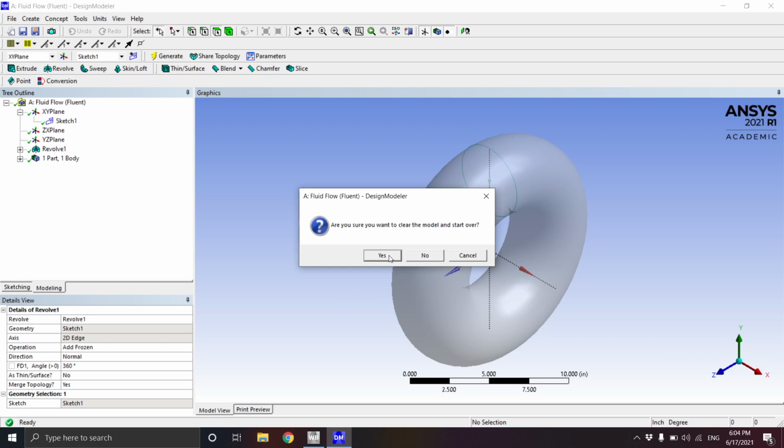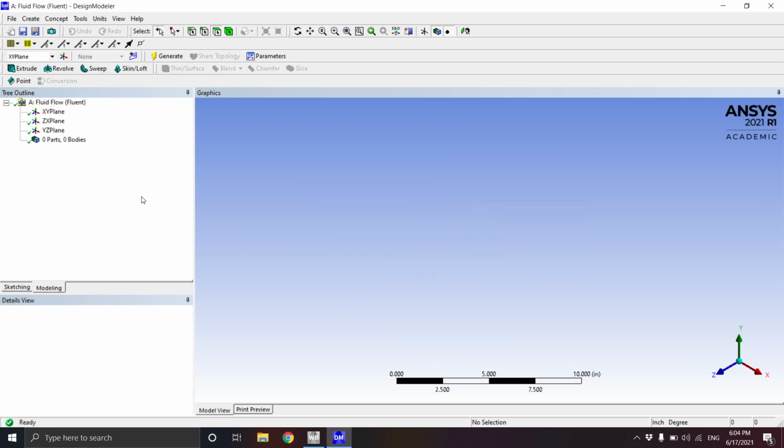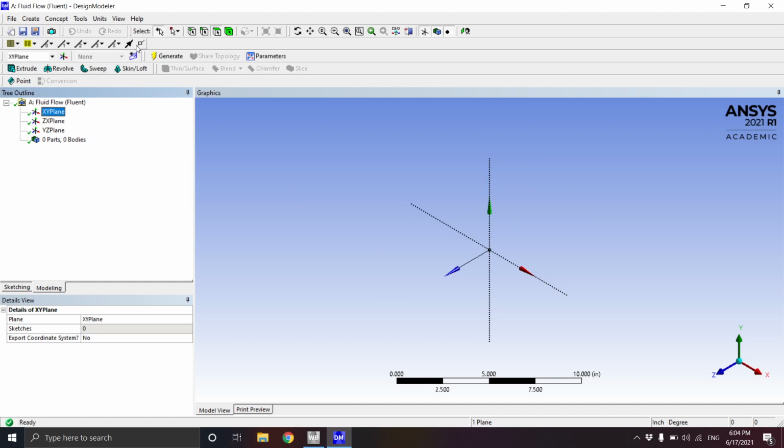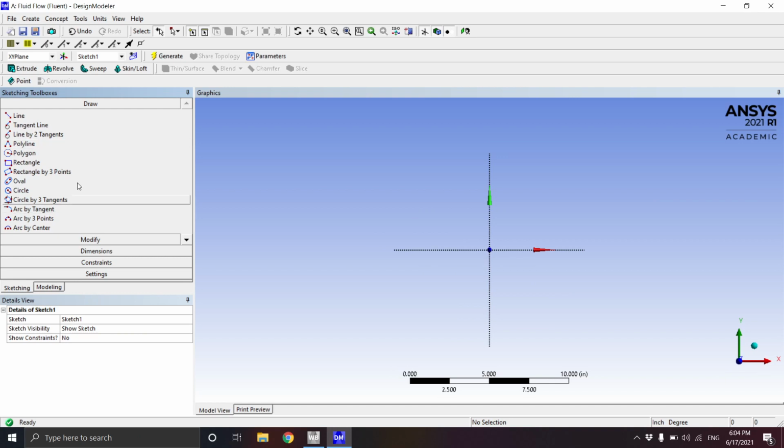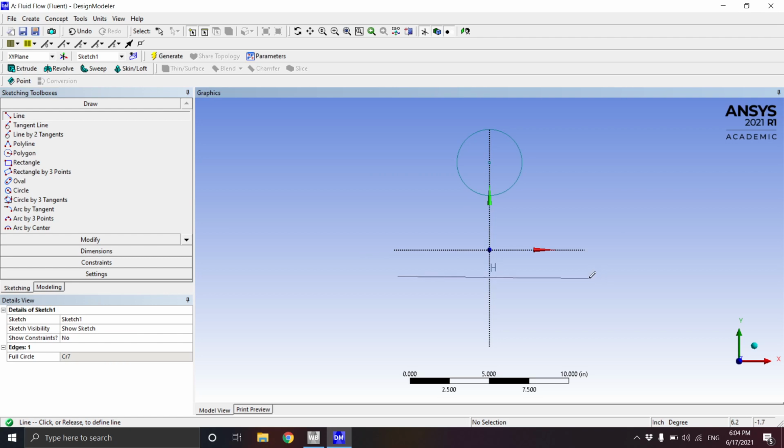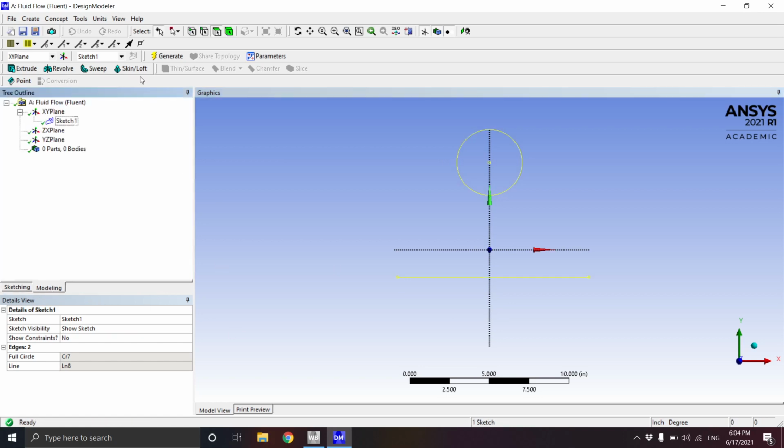Another cool feature, let's say that you're working with revolve, we generate a new sketch again. Let's go to circle. We draw this circle, and let's draw a straight line, not necessarily on top of our x-axis, but parallel to the x-axis.